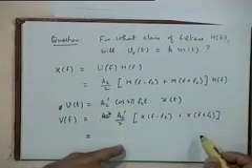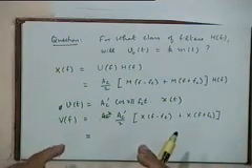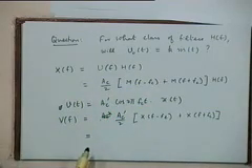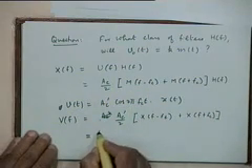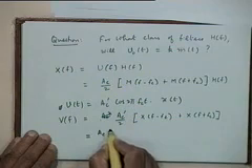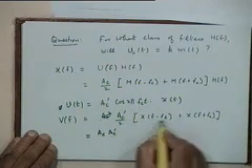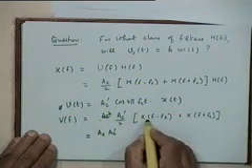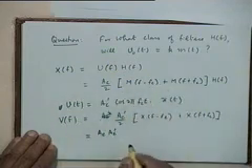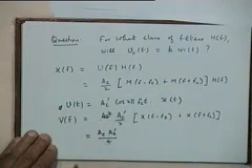These 4 terms that you will have here will contain 2 terms which correspond to the baseband component and 2 terms which correspond to the 2FC component. So let's first identify the baseband components. That will be AC into AC prime, right, because you are substituting for X of F minus FC from here, upon 4, right.